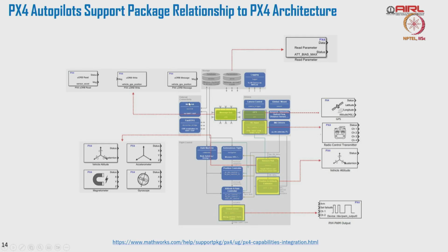It talks about how the message from the external interface, the data, goes into the real-time system, and then you have the corresponding drivers of those sensors. You can talk about all those drivers as being already built in the package. How your remote control, radio link control connects to your flight control architecture, how input can be provided, that's available here. And the radio link just passes on to your sensor hub and actuator hub, and then all that information goes into your flight control architecture.